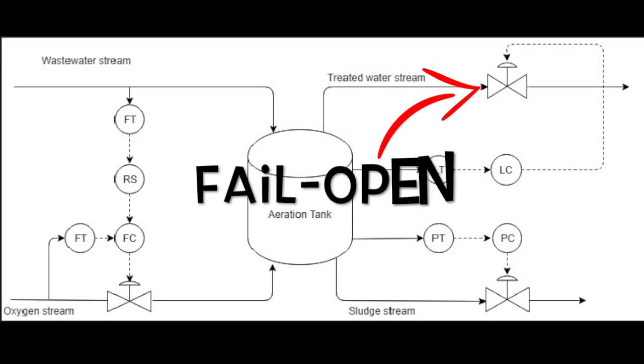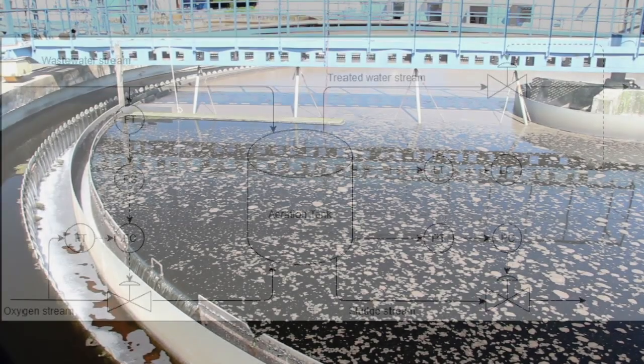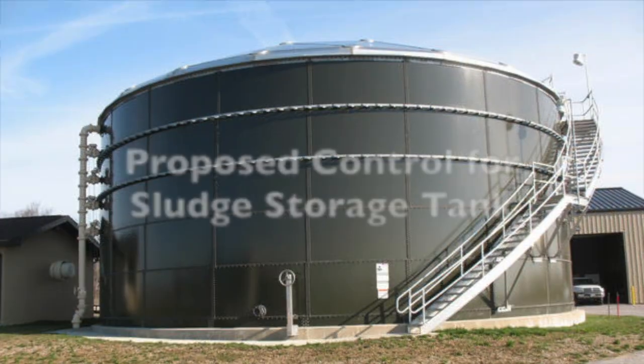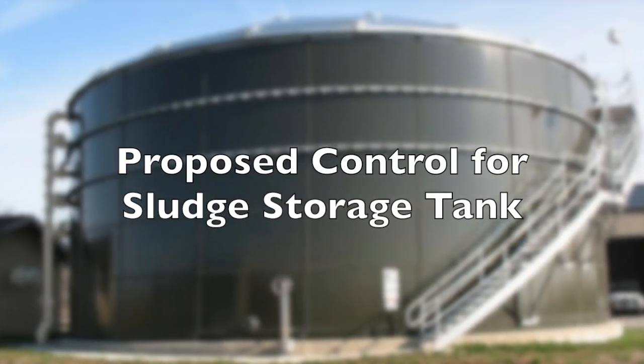The valve of the pipe should be fail open because if the valve malfunctions, the treated water will still be able to flow into the clarifier tank without causing the aeration tank to overflow. Let me continue with the proposed control for the sludge storage tank.